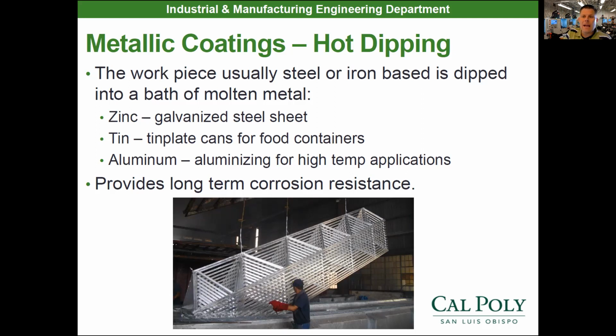Now, if you ever have any type of metallic coated material like zinc, you've got to watch out when you're welding that kind of stuff. There are harmful toxins that occur when you weld zinc or galvanized material. So you've got to remove that top surface before you weld anything that has been hot dipped or anything like that.